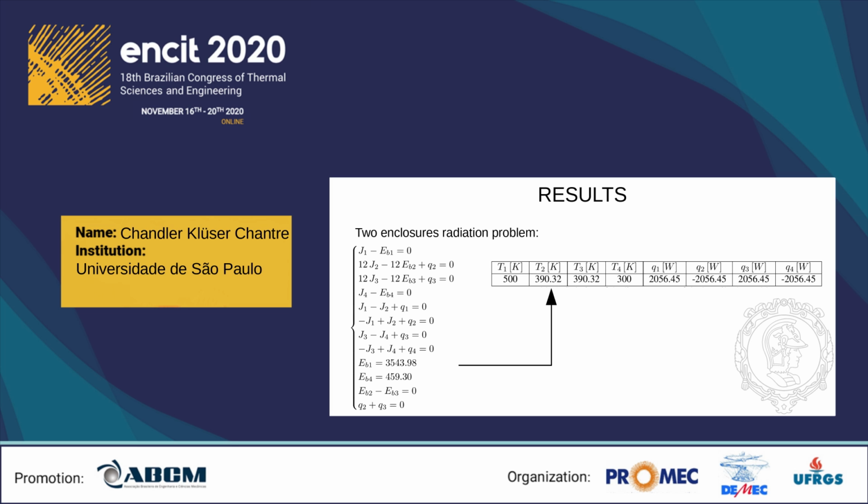Given that, we can write that their black body emissive powers are equal, and it is also known that the whole heat flux received by the second surface is given to the third one. Thus, summing the second surface heat flux with the third surface heat flux must give 0.